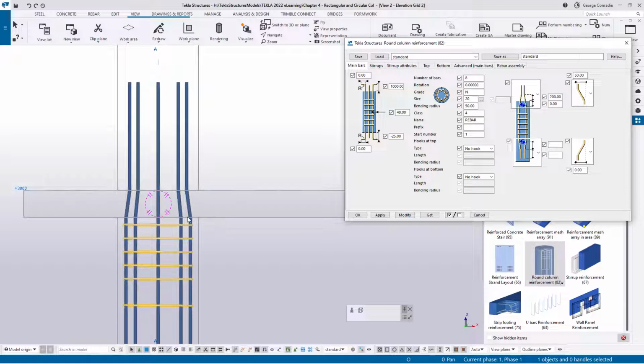You can see now we get the crank from the bottom to the top because it's a 200 slab. For the actual crank dimension itself, I do want to select outside to outside, not center to center. The value I'm going to use is 2 times the bar diameter, which is 23. Remember, the nominal is 20, but the actual is 23 because it allows for the deformation, the ribs on the side, and that's what we want to deal with when we want to fit one bar over another bar.